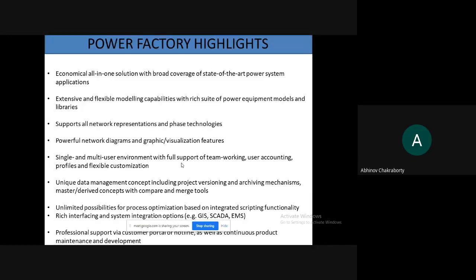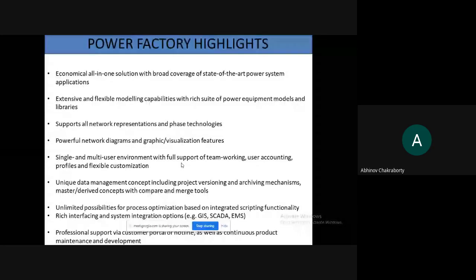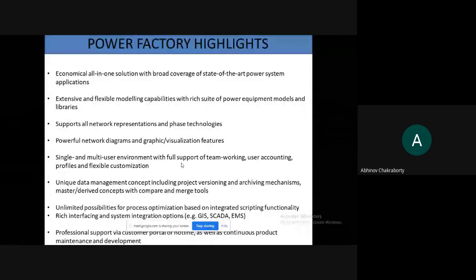Supports all network representations and phase technologies. When you talk about phase technologies, as we have briefed you, if you are talking about a three-phase system, we can have a three-phase three-wire system, and at the same time, we can have a three-phase four-wire system. Like at the end feeders, we can have a three-phase four-wire system as well. So these features are available out over there. You want to have your neutral shorted, it's there. You want to have a single phase representation, it's available. So you can choose your own phase technologies.